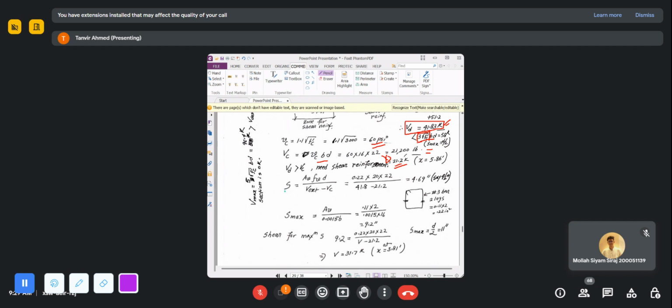তাহলে আমার ফ্যাক্টর অফ সেফটি ছিল 2, বাট এখানে আমার VC তো বড় না, বরং ছোট, VD এর চেয়ে ছোট। So obviously you have to provide shear reinforcement in this particular case. Okay, যদি আমার VC র ভ্যালুটা if it was more than or equal to twice VD হইতো,